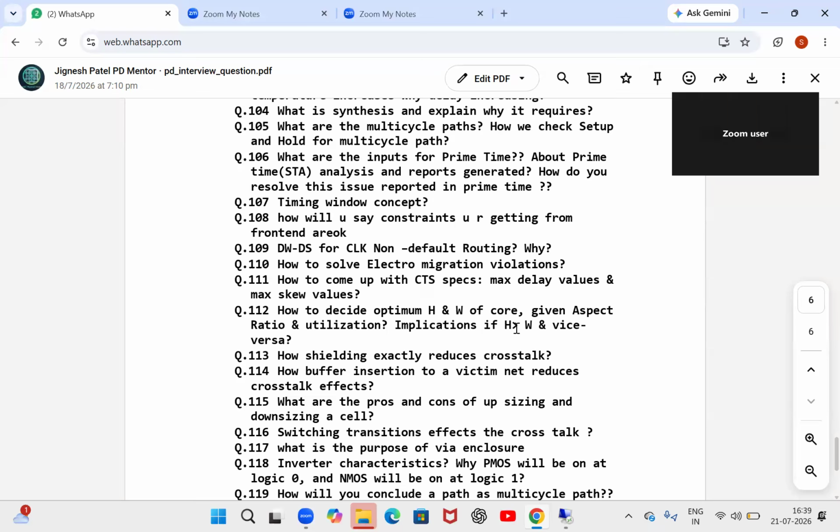It depends on how the module will sit, right? If the registers or pipeline are very big, then a square cannot accommodate that, and that might cause routing congestion or something. To reduce the congestion and for timing, we have to use a square.